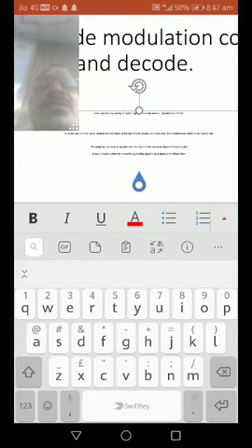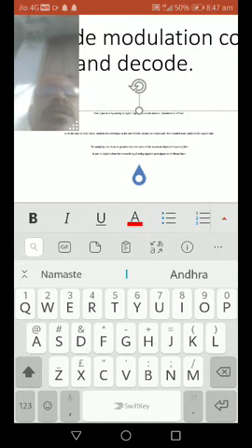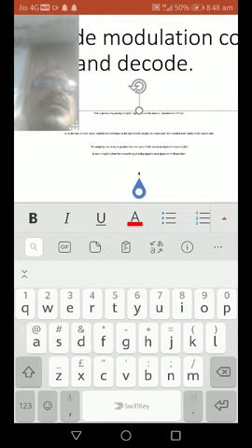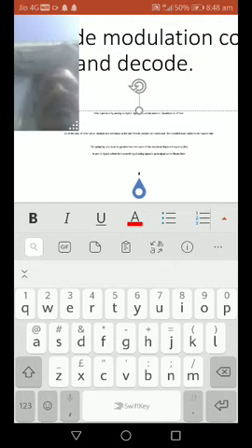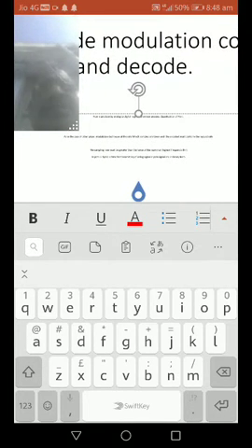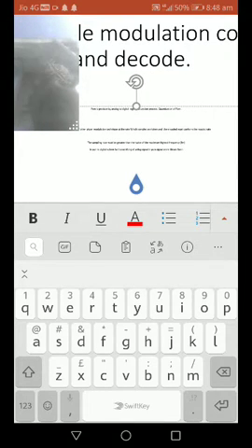The sampling theorem maintains the condition that the sampling rate must be greater than or equal to twice the maximum highest frequency, 2 fm. In PCM digital schemes for transmitting an analog signal, the sampled voltages of the electrical signal are converted into binary form, digital data of ones and zeros. The whole electrical signal of information is converted into binary by using this coded form, PCM.